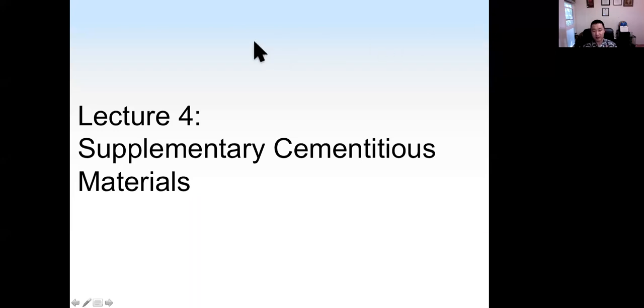All right. So lecture number 4. Today we'll discuss so-called supplementary cementitious materials. These materials can replace a certain percentage of Portland cement. Typically we also call them pozzolanic materials. We showed you what the pozzolanic reaction is in early lectures, and today we're going to discuss these materials.